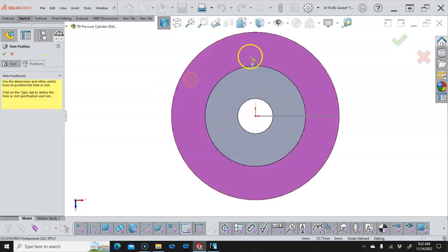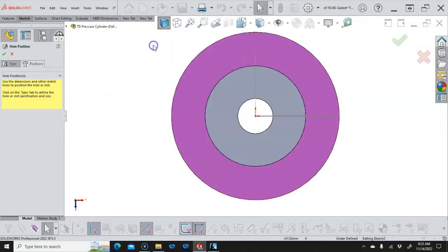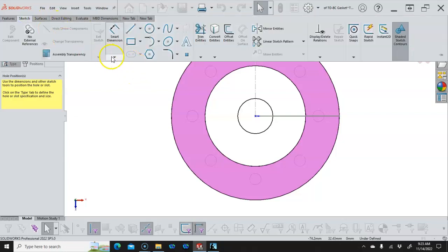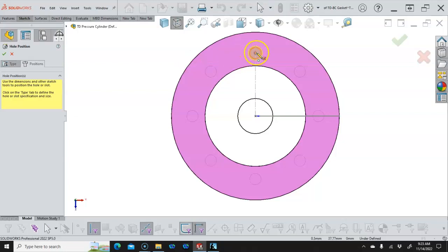And then the position comes down to, well, if we hide that, let's go with the hidden lines visible. And then back into the sketch, I'll pick up my points. And as I drag across those edges, the centers will highlight, and I can tie this to the other part.